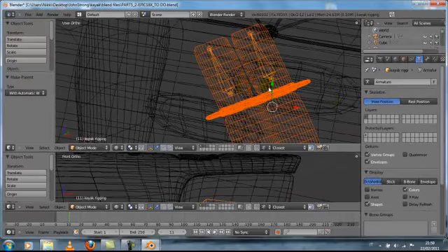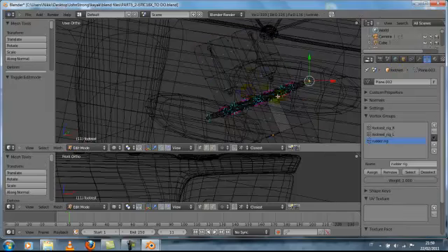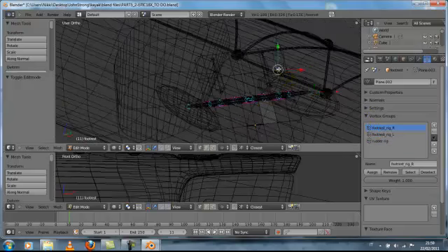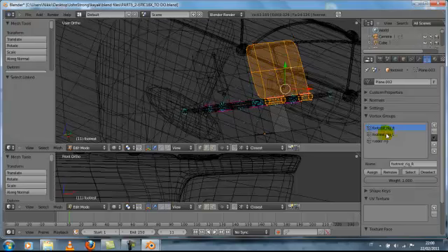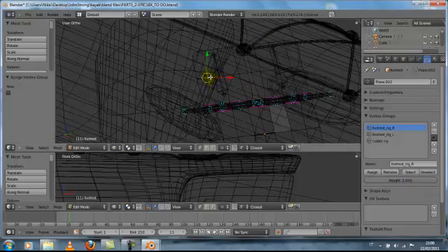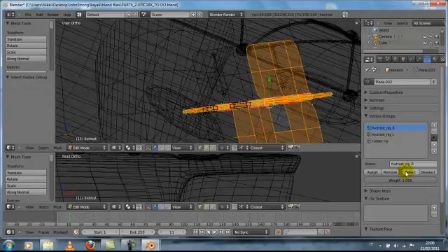Yeah, right. And now, when I select the footrest, go in edit mode, I have the footrest rig, and now what I do is hit L, select footrest rig and click assign, keeping the weight at 1. So we leave the weight at 1 and we do the same with the footrest L. Just assign, so check or select. Oh no.